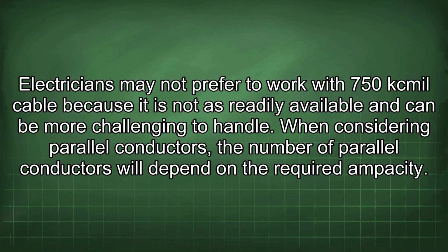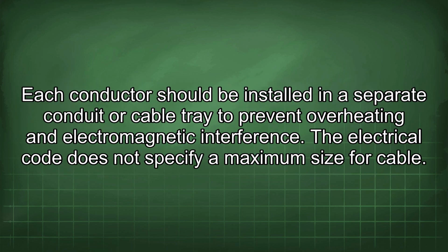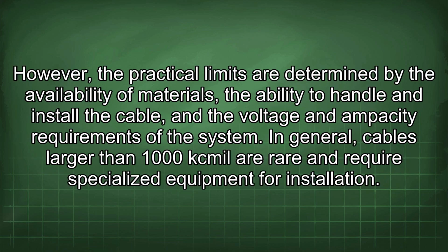When considering parallel conductors, the number of parallel conductors will depend on the required ampacity. Each conductor should be installed in a separate conduit or cable tray to prevent overheating and electromagnetic interference. The electrical code does not specify a maximum size for cable. However, the practical limits are determined by the availability of materials, the ability to handle and install the cable, and the voltage and ampacity requirements of the system.